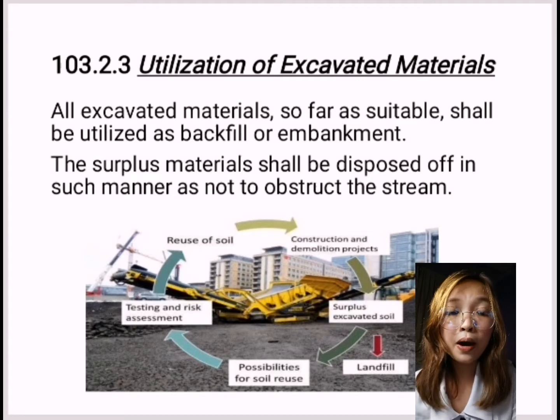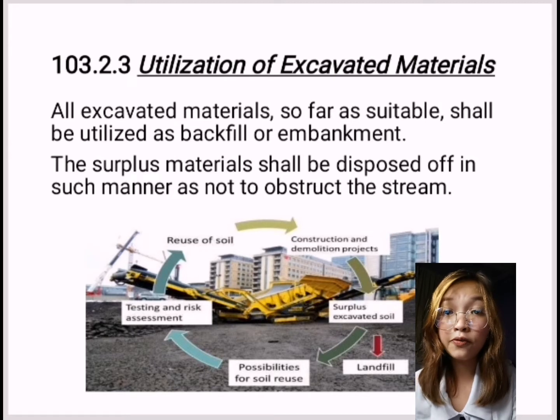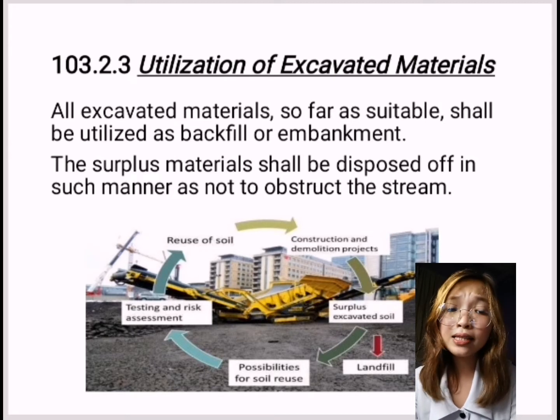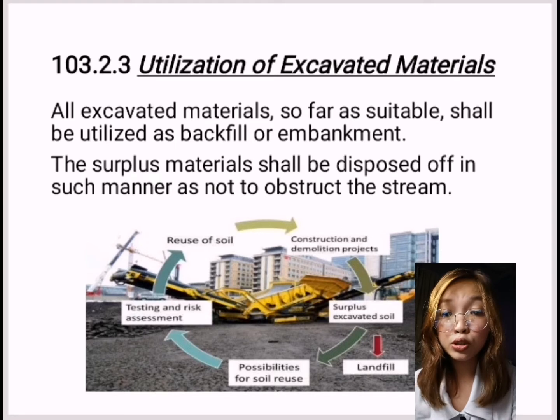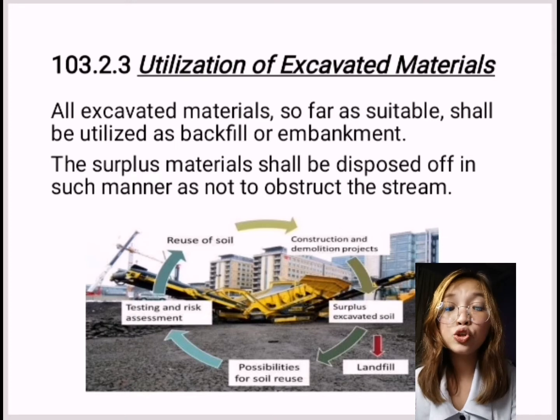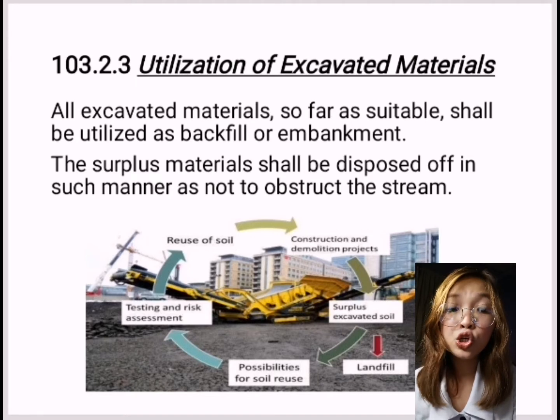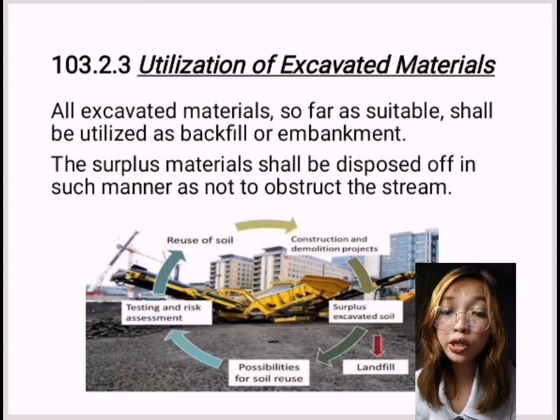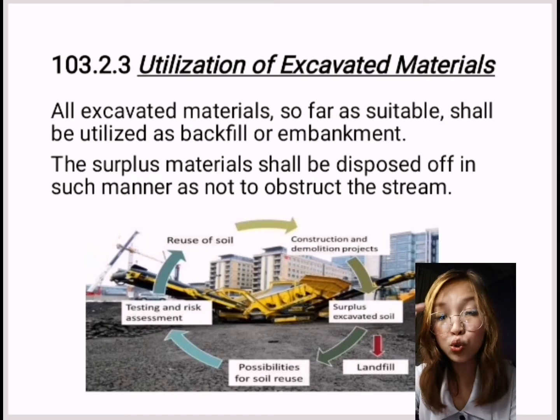So next, let's proceed to item 103.2.3. It is about the utilization of excavation material. So all excavated material, so far as suitable, shall be utilized as backfill or embankment. The surplus material shall be disposed of in such manner as not to obstruct the stream or otherwise impair the efficiency or appearance of the structure. So no excavated materials shall be deposited at any time so as to endanger the partly finished structure.